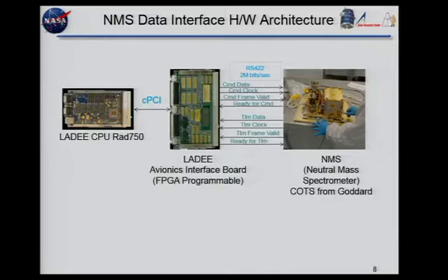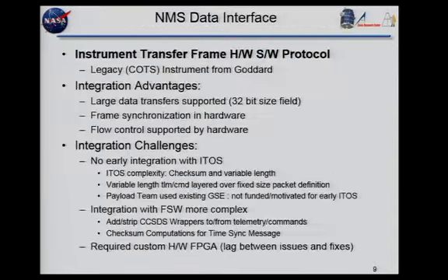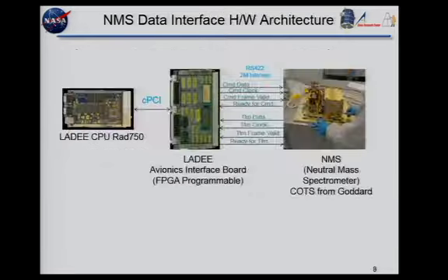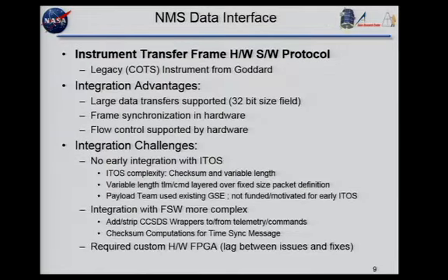It's basically a synchronous communication, so it has a clock that goes with it, and there's also a wire coming back from the receiver that says hold off on the data, so flow control. So it has data going out, coming back, a clock, and flow control. And you can get higher data rates when you have synchronous communication. I don't think I put the data rate, but this was, oh yeah, 2 megabits per second.